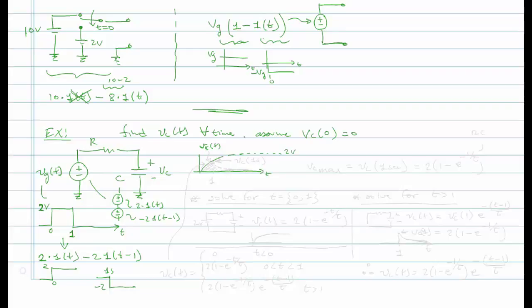However, we also know that if there is some voltage on a capacitor and you connect a resistor across that capacitor, the capacitor will discharge down towards 0 from its current state. And that is precisely what happens beginning at 1 second. At 1 second, the source goes to 0 volts, and we have no source really driving the circuit anymore.